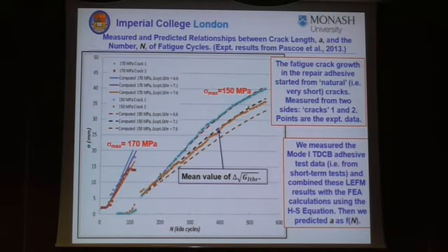So you can see the theoretical predictions agree very well with experimental points, both for 150 and 170 maximum fatigue stress in the cycle. And more than that, the theoretical work actually encompasses the scatter band rather nicely. So we can predict the results and the expected scatter. And we think that looks extremely exciting. And in the paper, we've done it for 2 different repairs from another group who have also done repair work. We find the same very good predictions.